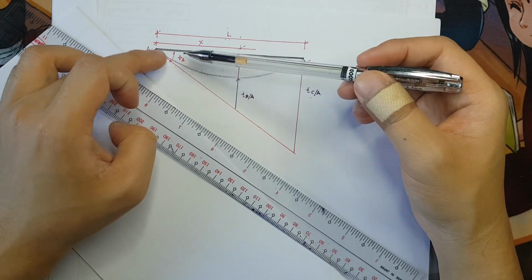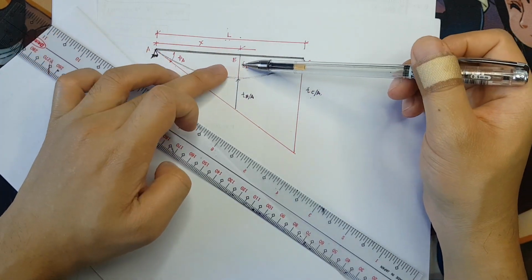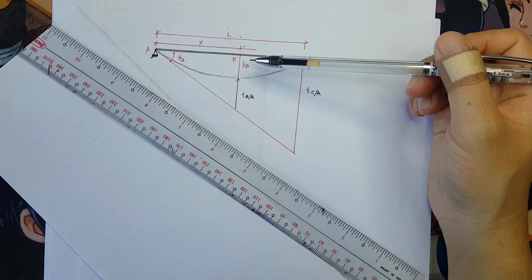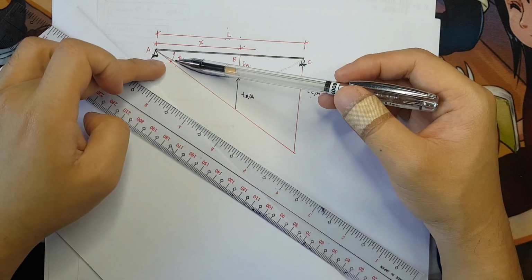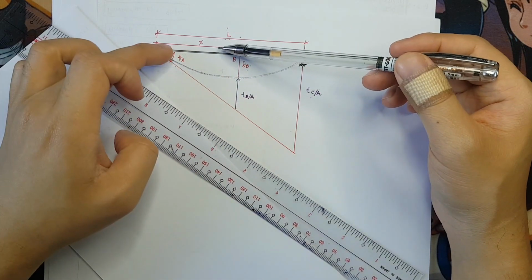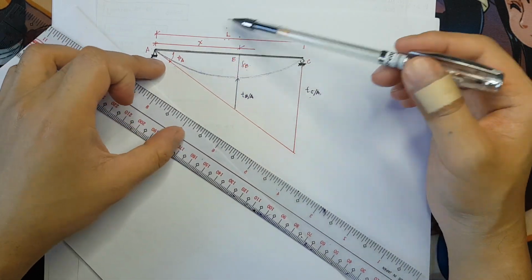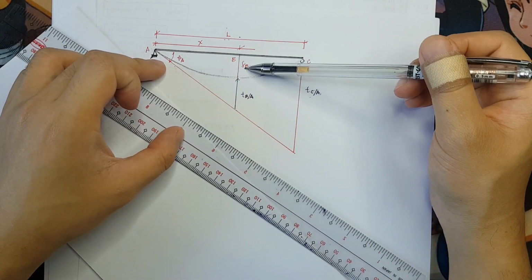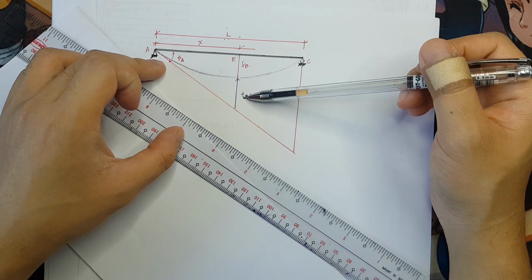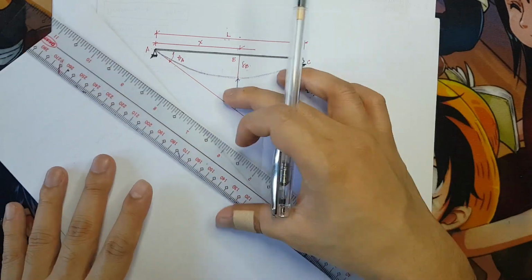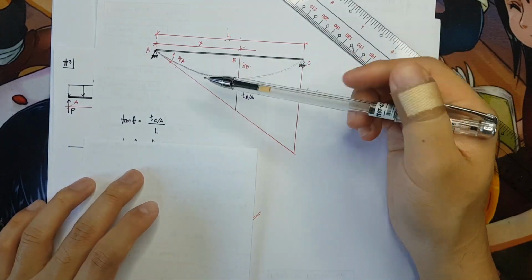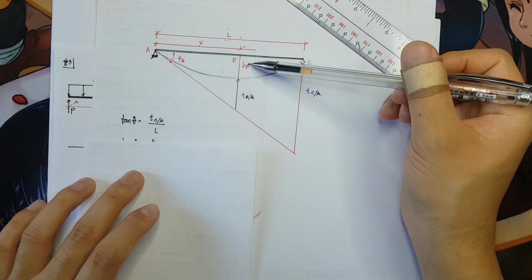So we can now solve the deflection at B by a trigonometric function of tangent. Tangent is equivalent to opposite over adjacent. So tangent theta is equivalent to the deformation at B plus the tangential deviation from point B relative to A. But we have three unknowns.